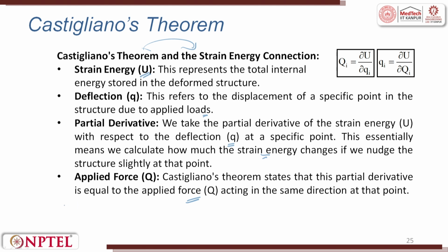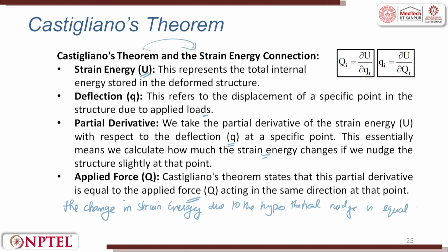In other words, the change in strain energy due to the hypothetical nudge is equal to the force that would be required to cause that actual displacement.